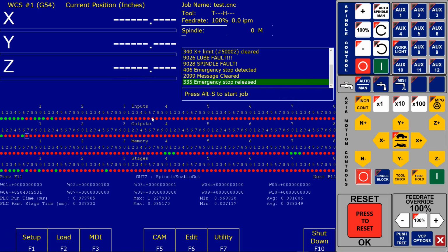All right. So now when we're going to create a custom PLC program, I'm going to make sure that I don't end up putting it onto anything that's not being used, because chances are there's probably logic in the PLC program that's looking for that, and I don't want to override it.